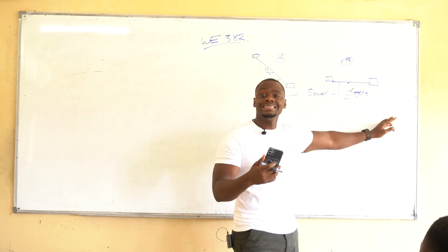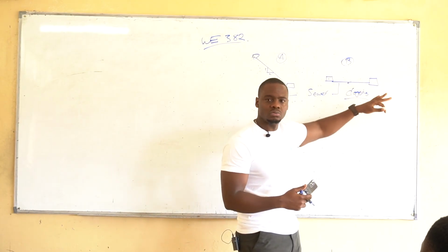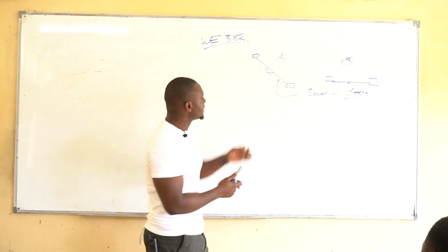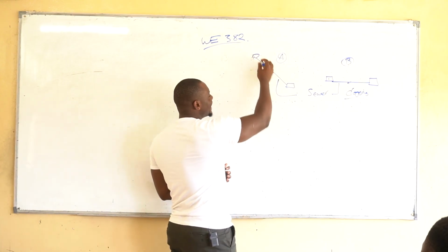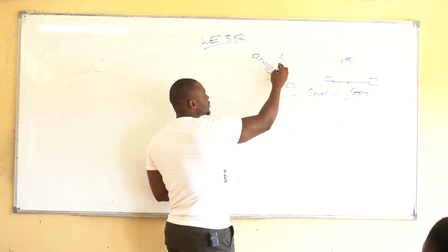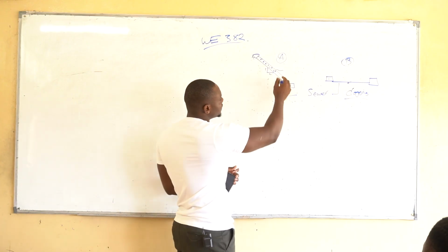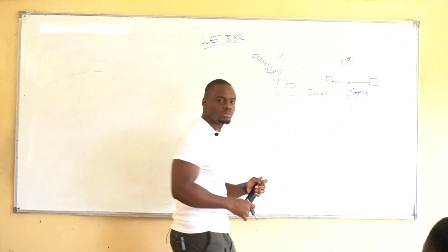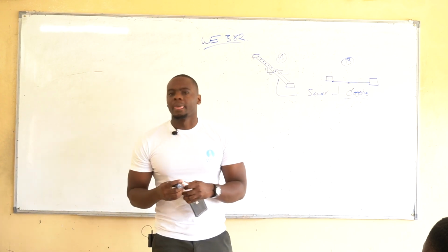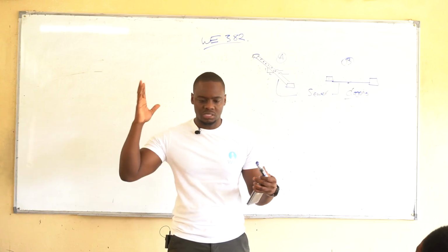So if there isn't enough gradient, you're likely to clog your pipes. But with this one again, you cannot just put it at any angle because there are sediments that you're carrying inside, and because of that, abrasion happens, and so you expect that your pipes would, in a short while, probably burst.